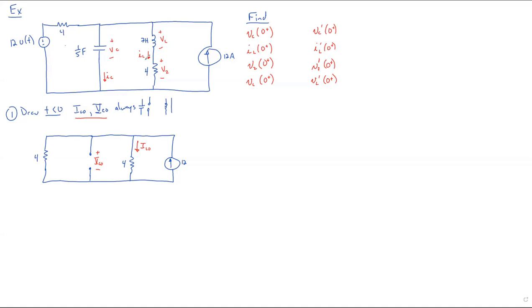Now, there's a lot of ways we can analyze this circuit. We could analyze it by doing a source transform on the right. We lose our IL, but we could at least simplify things to a big round mesh, one mesh. And then you could find VC naught. And then once you knew VC naught, that's the same as the voltage across the 4 ohm resistor. So you can find the current. But it's even easier than that.